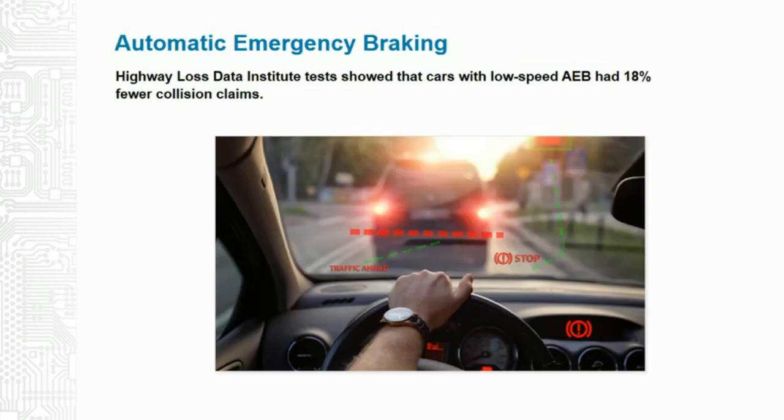Okay, let's go to one specific feature, automatic emergency braking, which I mentioned briefly a moment ago. Many drivers can now rely on this feature. On-vehicle sensors, including radar, cameras, and lasers, detect an impending forward crash with another vehicle in time to avoid or reduce the severity of a crash. The first interaction with the AEB system is an alert that the driver will get to take corrective action. Then the system will supplement the driver's braking to avoid the crash.